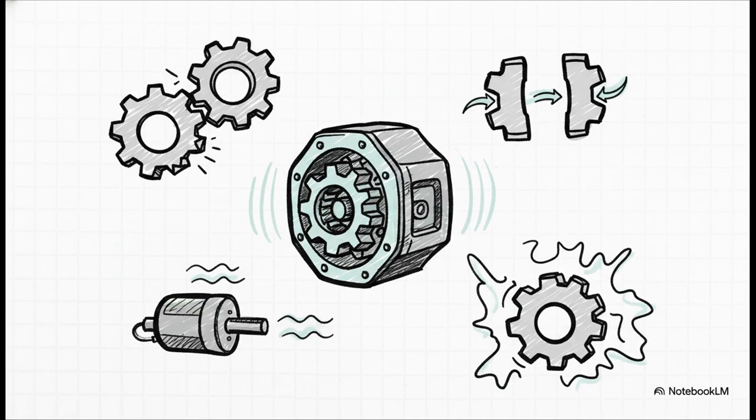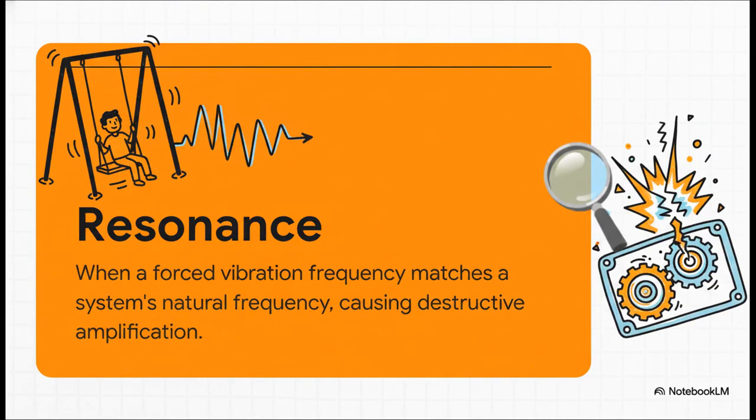Look, some noise is just going to happen. The standards often suggest that anything under 85 decibels is pretty normal. But if you're getting excessive noise, that's a huge red flag. It could be pointing to a manufacturing problem like sloppy tooth finishing, or something much, much worse, like you're running dangerously close to a resonant frequency. And this is the one phenomenon you absolutely want to stay away from. Hitting a resonance frequency is like pushing someone on a swing at exactly the right moment every single time. The swings get higher and higher until the whole thing breaks.